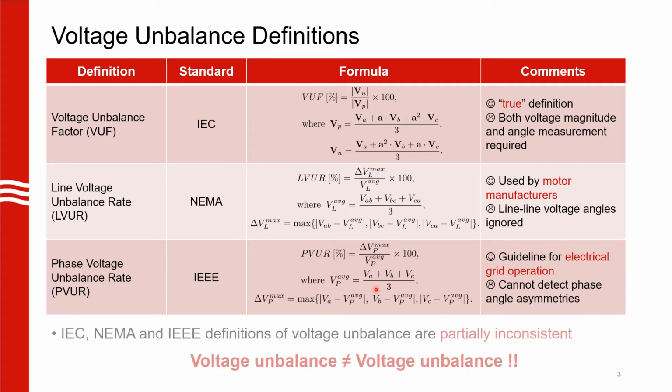Now what is interesting is that these three definitions of voltage unbalance are partially inconsistent. What this is trying to say is that operating points that satisfy one standard do not guarantee that they are going to satisfy the other two standards too.